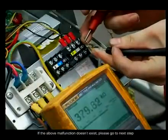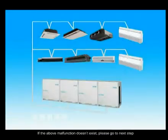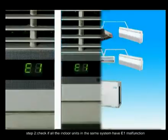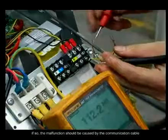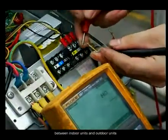If the above malfunction doesn't exist, please go to next step. Step 2. Check if all the indoor units in the same system have E1 malfunction. If so, the malfunction should be caused by the communication cable between indoor units and outdoor units.